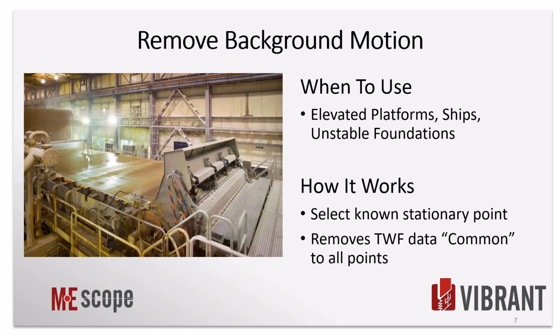But another good place to use this, a lot of times people do measurements for generators or engines on ships, oil rigs, same kind of concept. Obviously, it's moving with the ocean, so we want to get something in the horizon, if at all possible, or something within the hull of a ship that is not generator or engine related, to select those points and then remove the background motion.